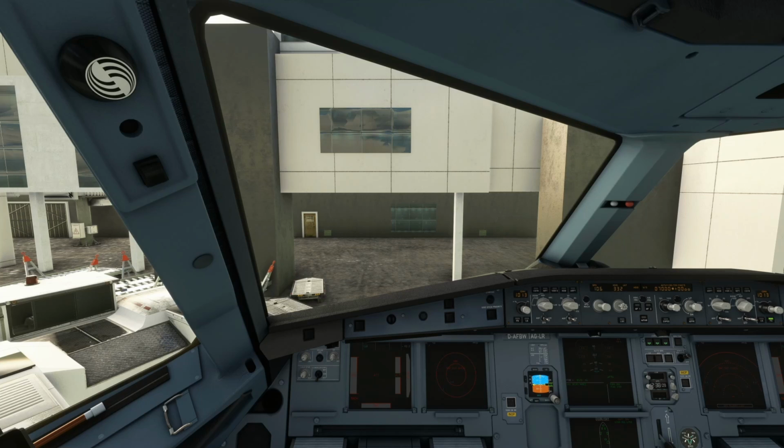That's a simple FCU. Usually FCU is the panel that's most used during the flight anyway. So if you want to prioritize FCU and EFIS, it's worthwhile, because you can change some of the functions here, the radio, the range here, very easily, and even the FD, LS, and constraint, and then of course the QNH. I haven't found this setting for the ISIS, but that's something I need to find later on.